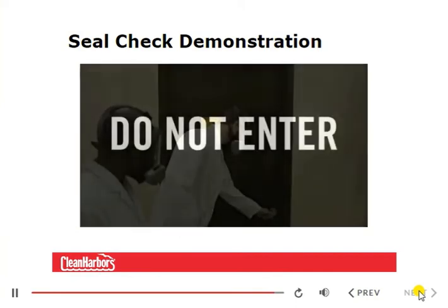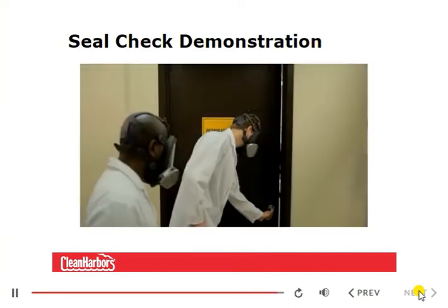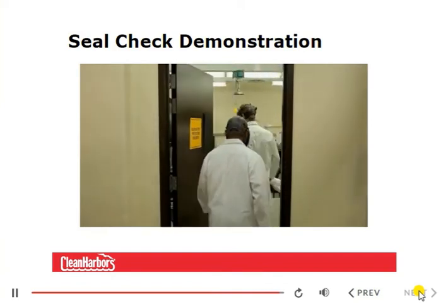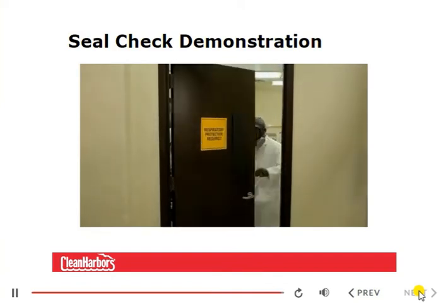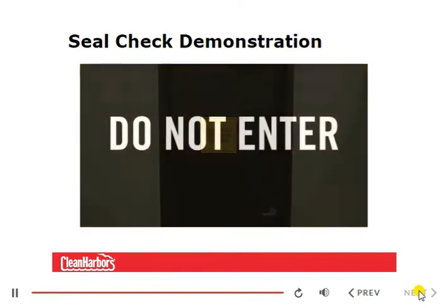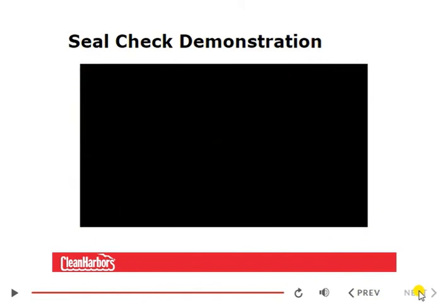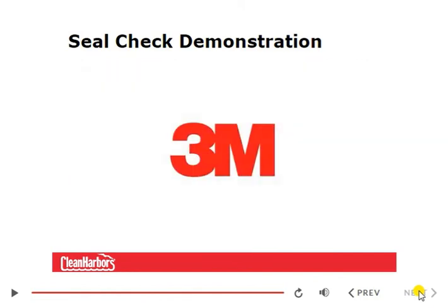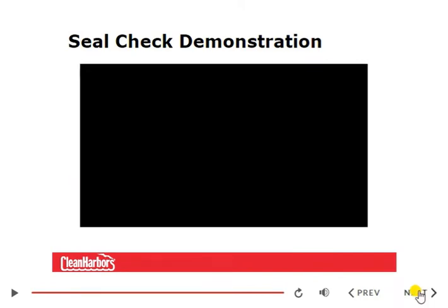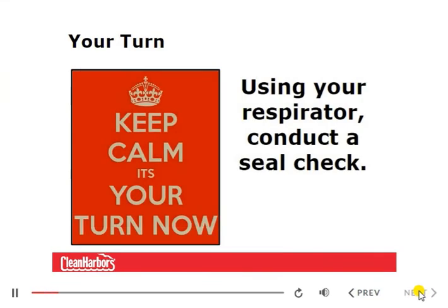Once both positive and negative pressure user seal checks have been confirmed, you may enter the contaminated area. Please note, if you can't achieve a proper seal, do not enter the area. Instead, see your supervisor. Now it's your turn. Using your respirator, conduct a seal check.